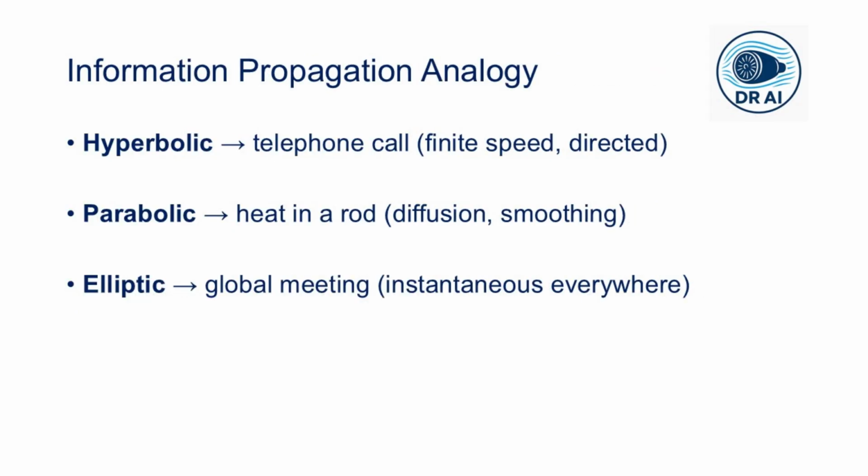Now, at its core, CFD simulates how information travels in a fluid. We are not solving static equations, we are simulating how a physical quantity at one point influences another. In hyperbolic equations, information propagates at a finite speed along the characteristics. While in parabolic equations, the information diffuses. In elliptic equations, however, the information instantly affects the whole domain.